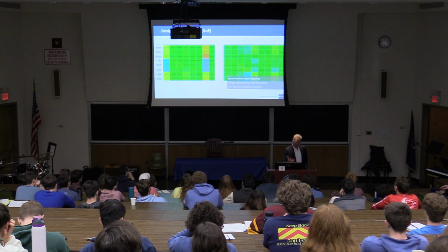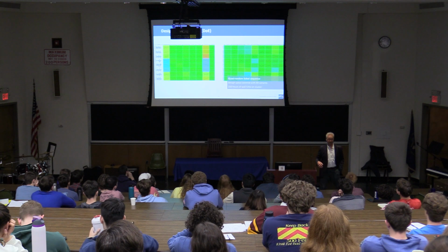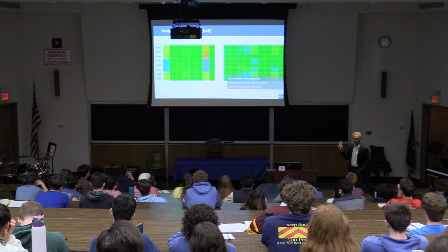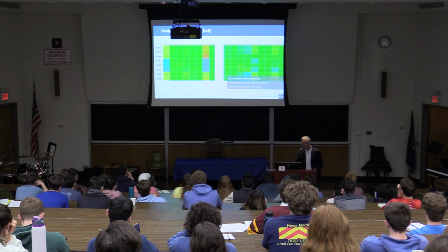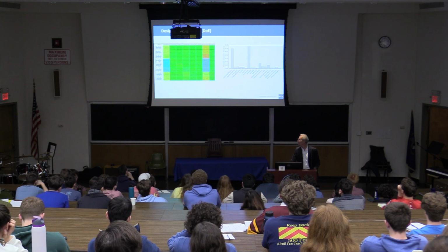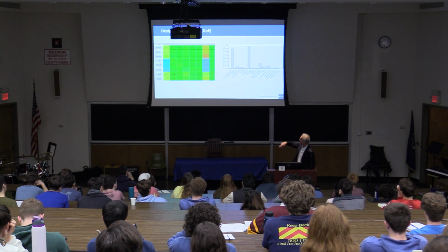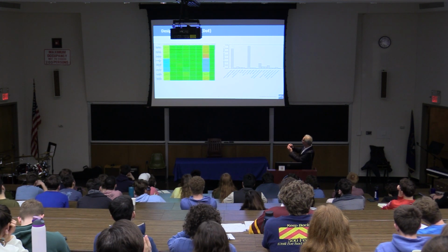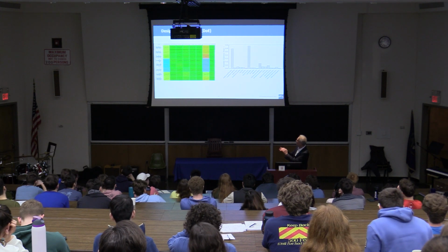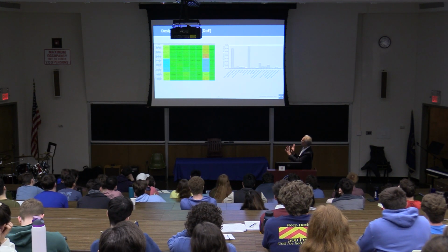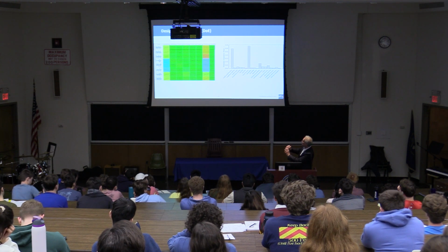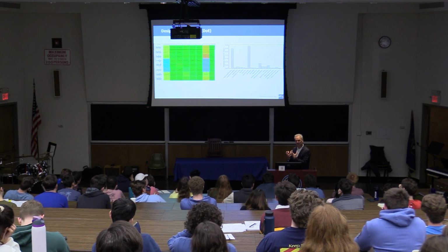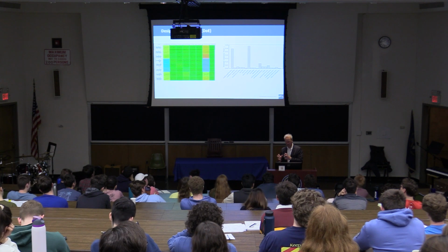And then you run the design of experiment, as I explained, and you would typically get pictures like this. Lots and lots of data points that you now have to try to understand. Let's take a closer look at this one row here. It gives you thrust as the ordinate versus different parameters. As you can see from the coloring and from the correlation lines, if they are very horizontal and the coloring is green, it's not such an important parameter. But if it's yellow or orange or red or blue, there is a lot to be changed when you change a certain parameter.